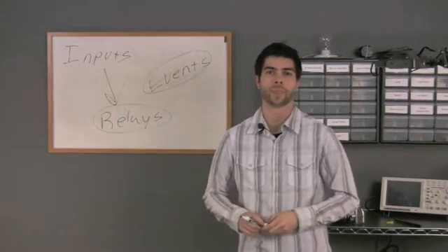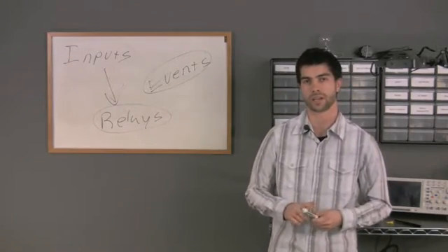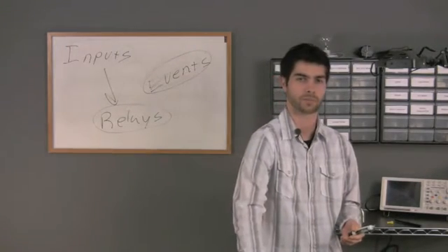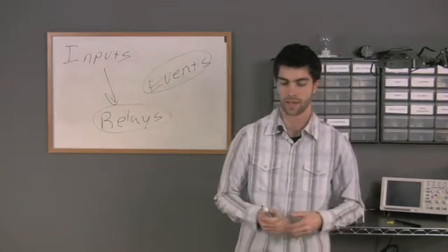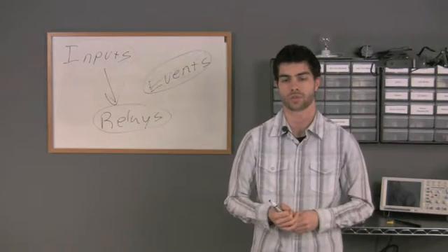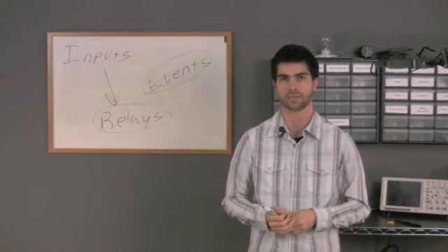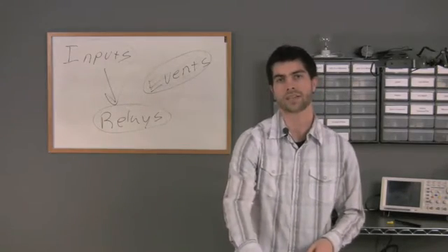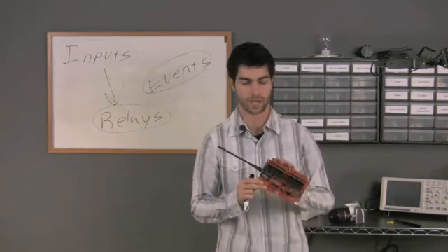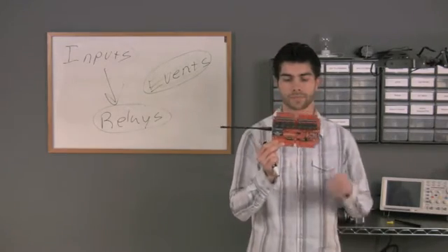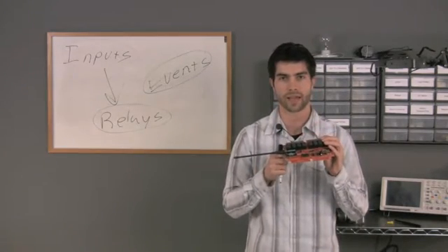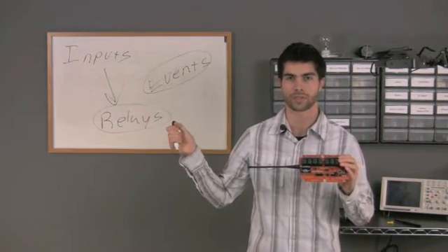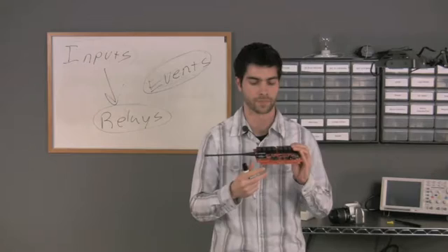Now remember, that key fob is basically triggering one of the inputs of the board. And if you're using a key fob controller, then you need to know how that key fob actually works with the reactor. Think of it as the reactor has 8 valid inputs. This happens to be a key fob controller here. They have 8 valid inputs that I can apply contact closures, variable resistance sensors, or 0 to 5 volts to.